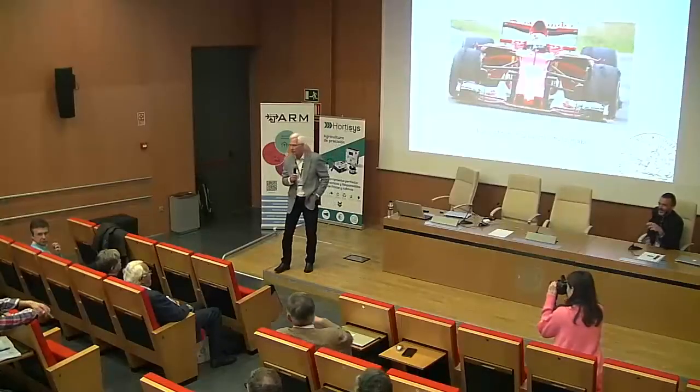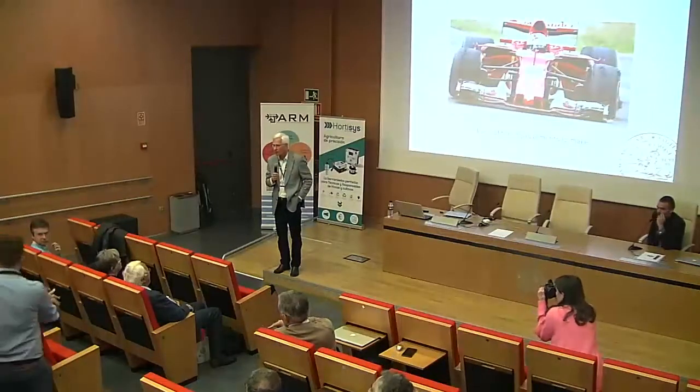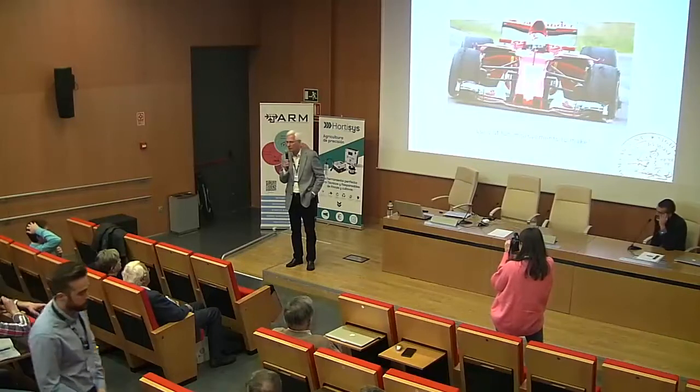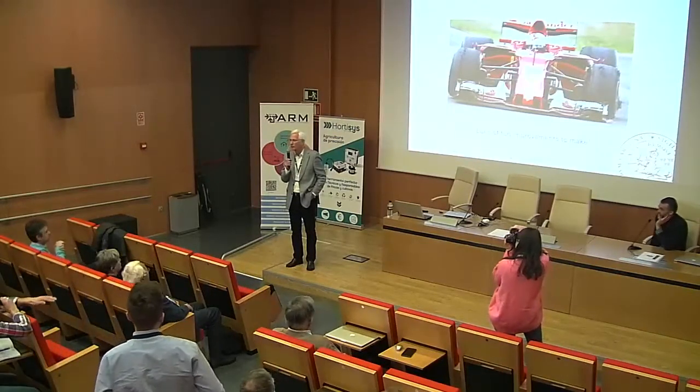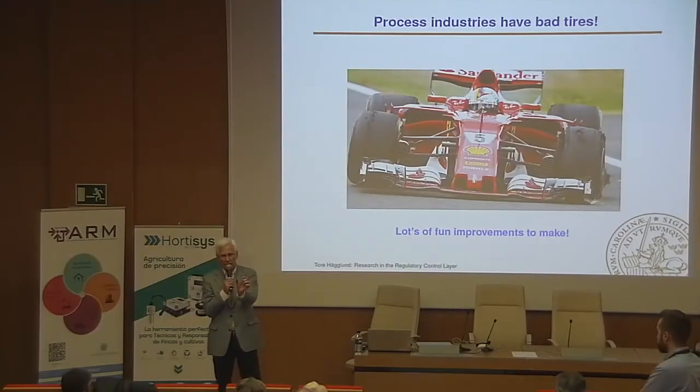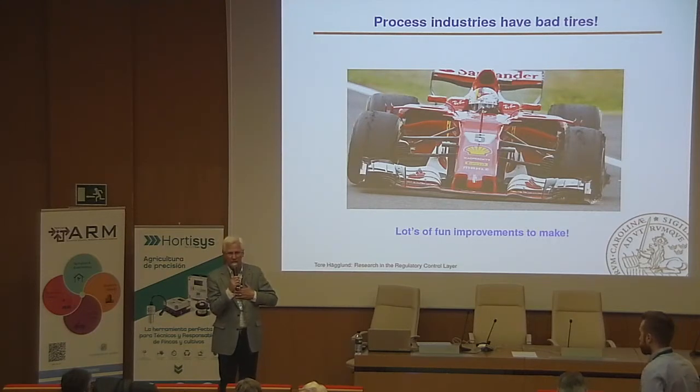Yes. In your ratio controller, is the switching still going on during the steady state all the time? No. I think I showed you some simulation. If you have this hysteresis, if I'm now a master and you're a slave, we will not switch until your error is a certain amount larger than mine, so to say. So there is a hysteresis. So in steady state, with no noise, nothing, there is no switching.